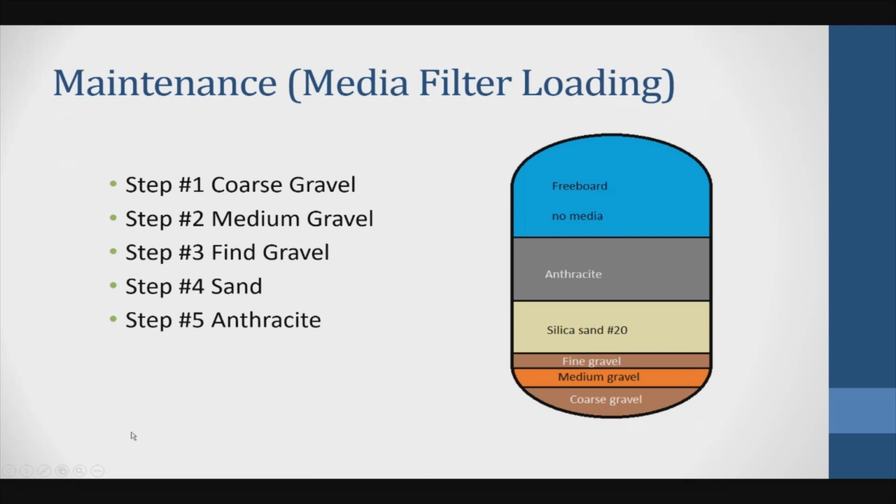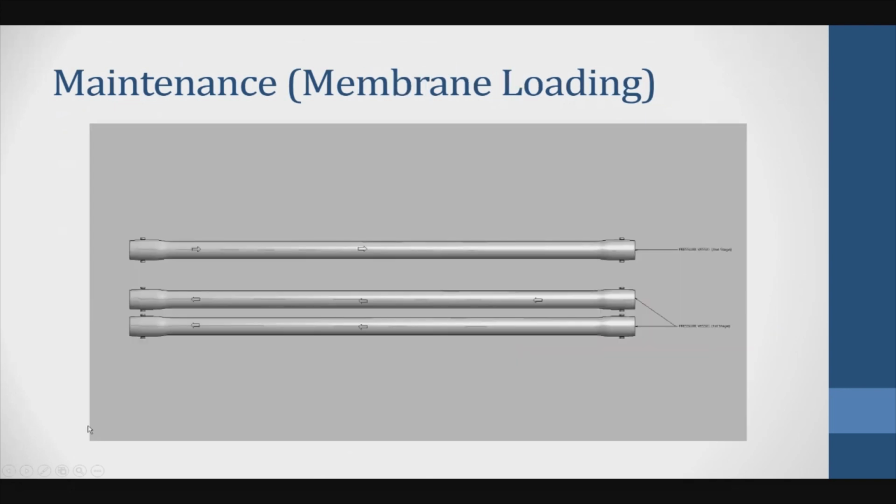Now, those are the pressure vessels that house the membranes. In a system like this, when we're going to load the membranes, as an example, in the 8-inch membrane system, we do not load the membranes beforehand because the system is going to be really heavy. We just keep the membranes fresh in the original packaging, where they're maintained, and they don't get dry or polluted.